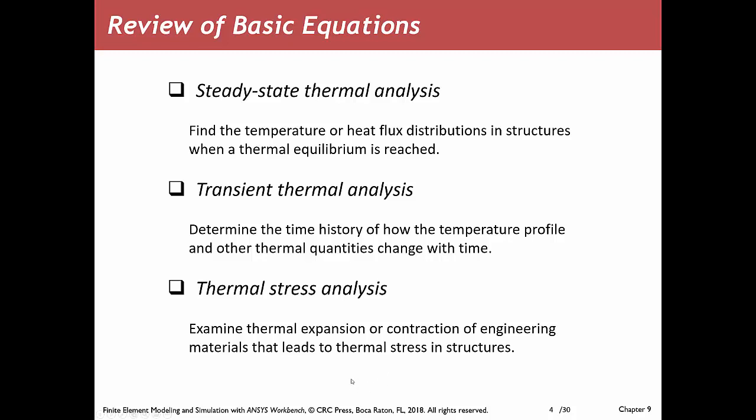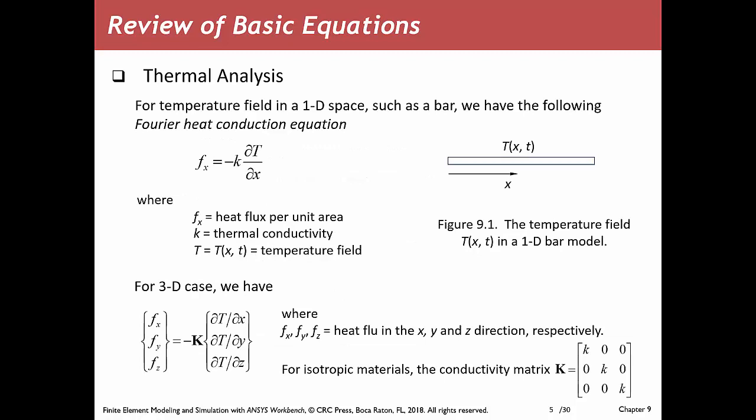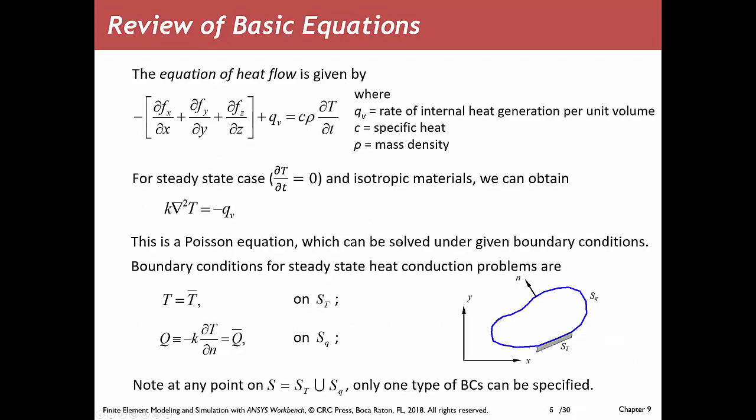So we want to see how we can do this analysis in ANSYS. Again, you are familiar with heat transfer. This is the heat conduction equation, K, and this is the variation of the temperature with respect to X. Of course, time here is not considered as a state. And F represents the heat flux, very similar to the finite element formulation that we did before, but K here has a different definition. It has to do with the conductivity, right?